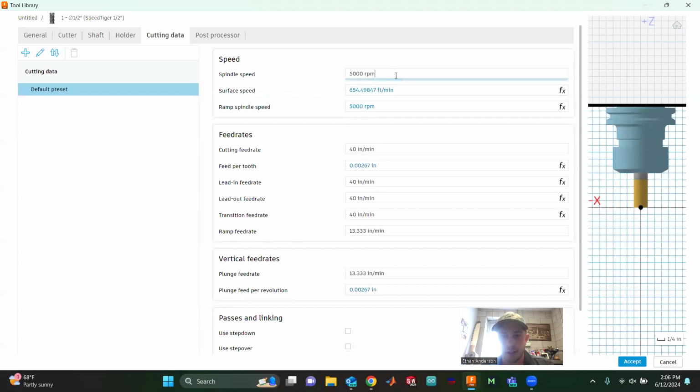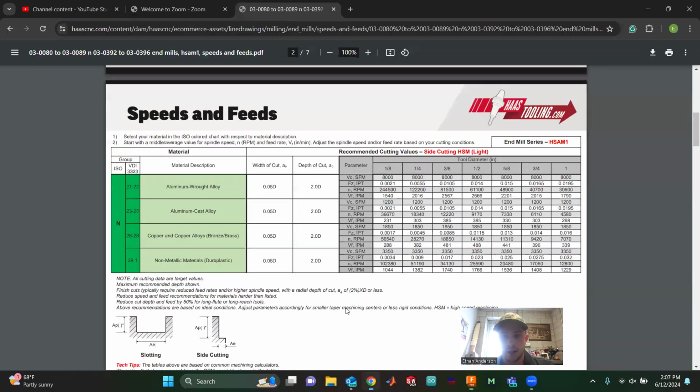Okay, so let's set this back up to 10,000. And we're going to go on here and it says VF. VF is going to be your cutting feed rate. The best thing to do is set it by surface speed and your inches per tooth. So this value and this value, these two get combined to make these two. In this case, I typed in an RPM only because we can't reach this RPM. If we could have reached it, I would have typed in the surface speed in Fusion.